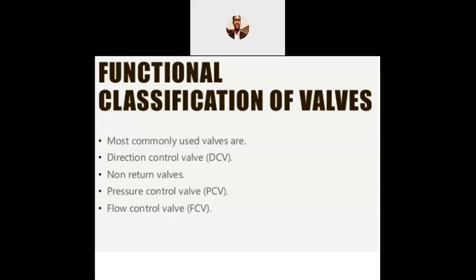Maybe in the sump. Correct. Am I right, Fernandez? In the sump, when lifting water, at the end of the sump pipe we keep a non-return valve, or we also call it a one way valve. That means once you start sucking the water from the sump, the water will start flowing. Once you switch off the motor, the water will stop there itself.